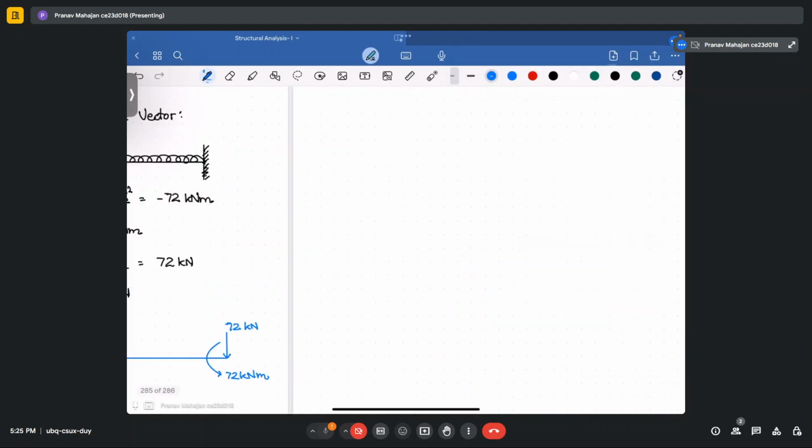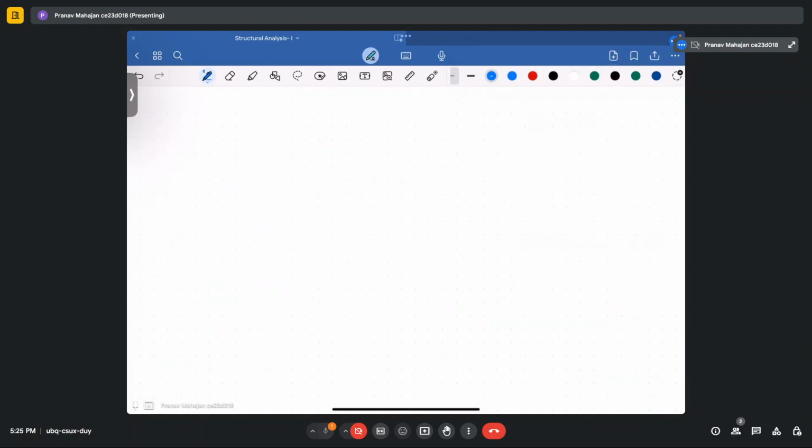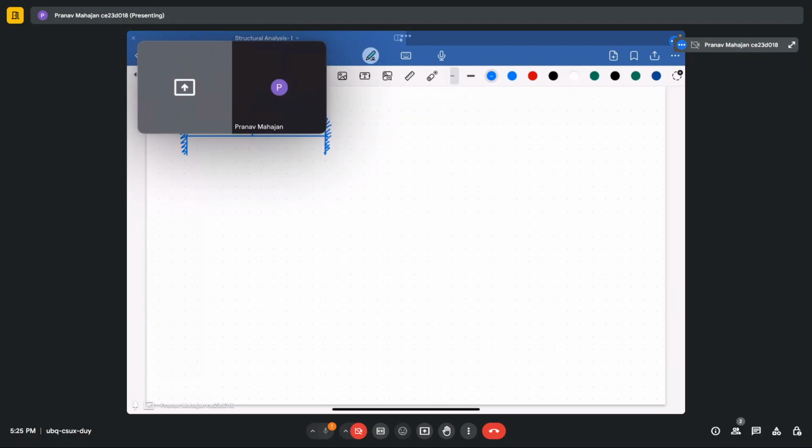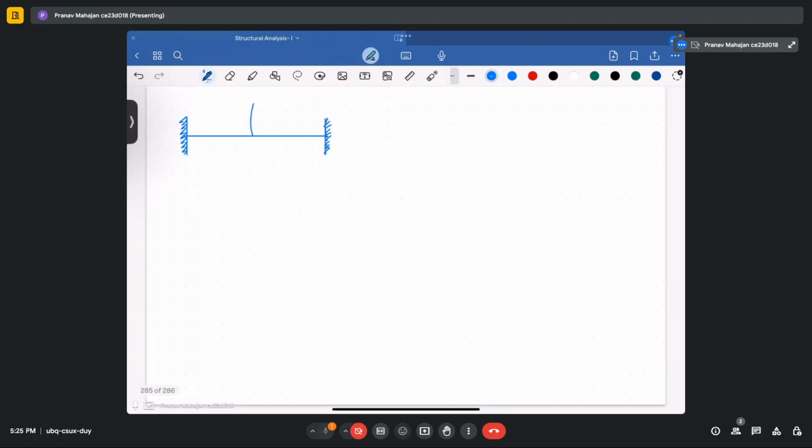Now for member BC, again due to point load, your FEF 1 will be equal to PL square upon 8, PL by 8, sorry.